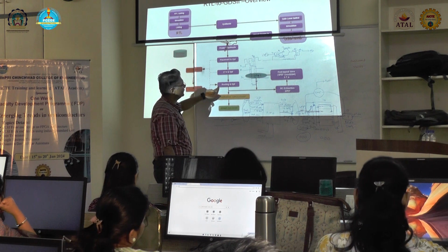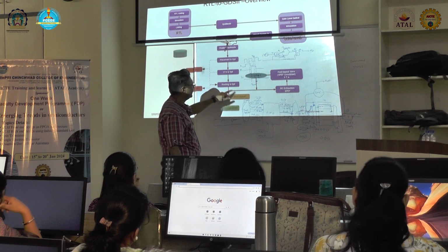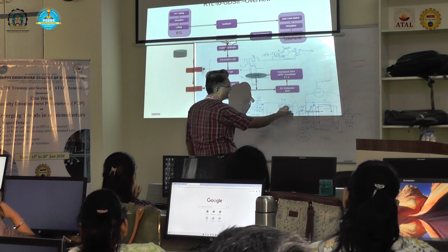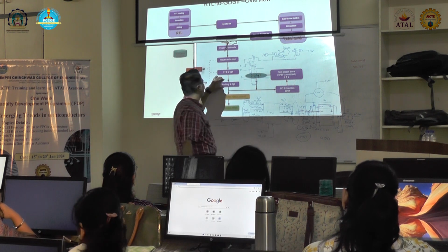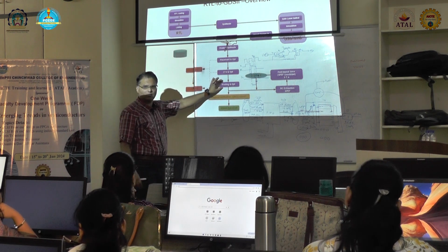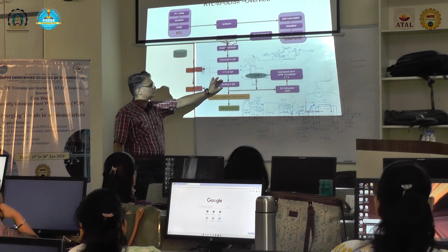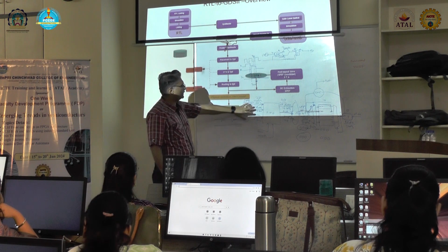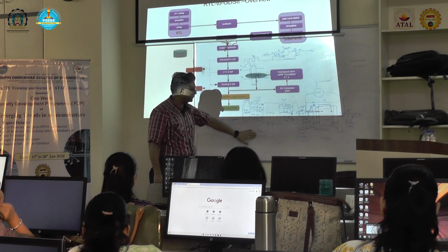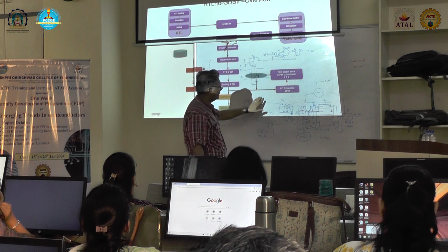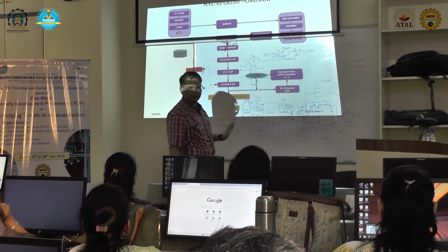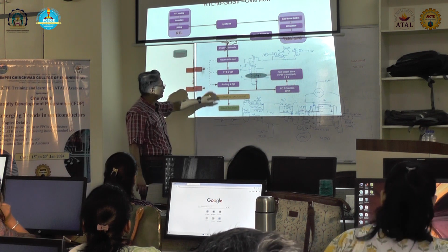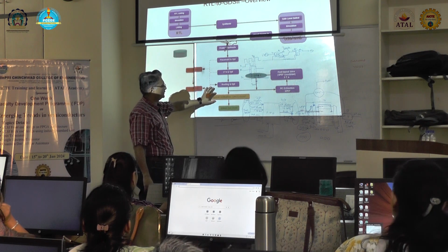Okay. Then what we do is the signal routing. Routing is nothing but these write enable, write data, read data signals. These are the signal routing that is happening at this stage, the last stage. So finally you have connected the clock, these signals, and the power signals also, right? After that is done, you go into the physical verification.